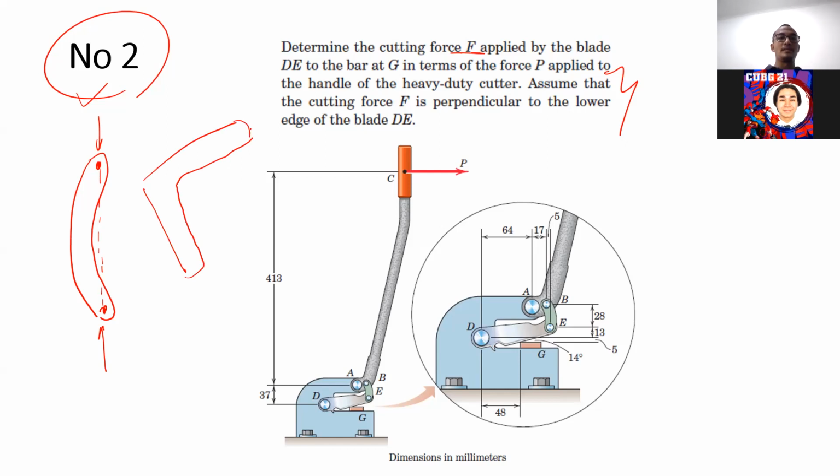The same thing applies for this kind of shape as well. Sometimes a two force member can be in this kind of shape. You have two joints at both ends, the force only comes from both joints, and there is no friction at both ends. So the force is supposed to be in a straight line. If it's under tension, it's supposed to be like this. If it's under compression, it's supposed to be the other way around. Like this. You get it, Rafi?